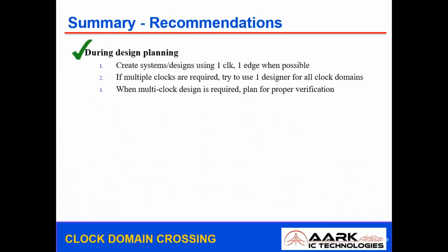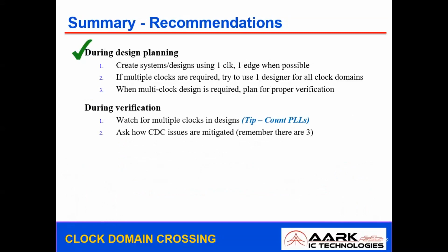So what are the things that we need to apply during the design? Create the system or design using one clock, which is already addressed. And during the verification, watch for multiple clocks in the design, and proper care needs to be taken with respect to the signals which need to be synchronized. These need to be properly addressed in the verification plan. Ask how CDC issues are mitigated.